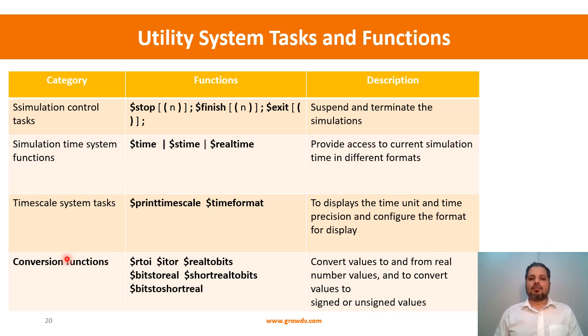And then you have a bunch of conversion functions. These conversion functions convert from real values to different types of signed and unsigned values and bits. So when you are dealing with real numbers, you can remember that you have functions to convert between different formats.